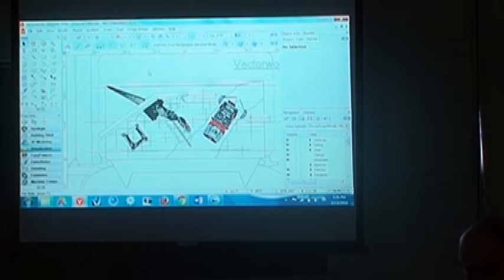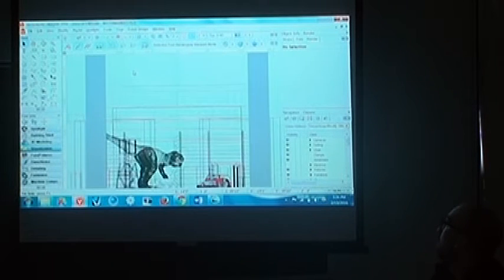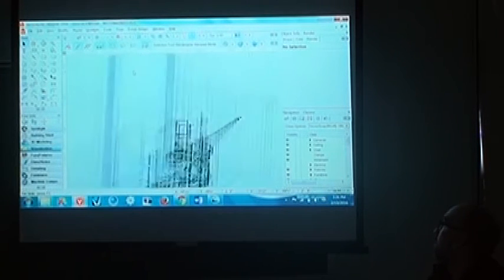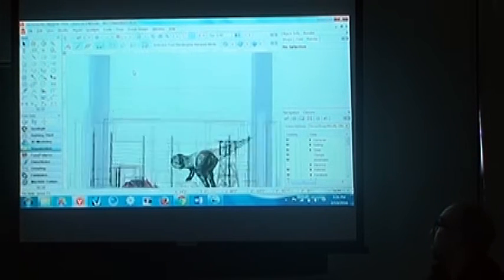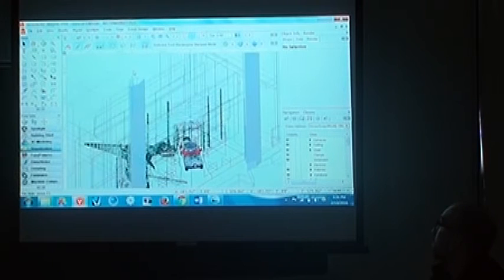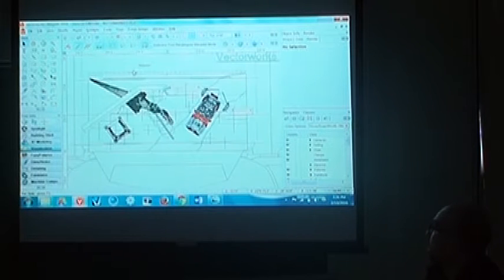And then the last thing here is a bunch of useful shortcuts if you're not aware of them already. If you're not aware that your number keypad on your keyboard will cycle you through the standard 3D views, left isometric, front, right isometric. That's just going around my keypad, 1, 2, 3, 6, 9, 8, 7, 4, 1, going around. And then 0 takes me back to top plan.